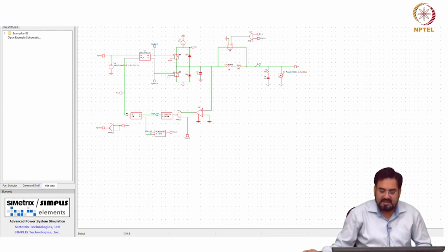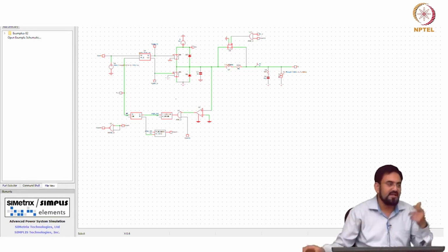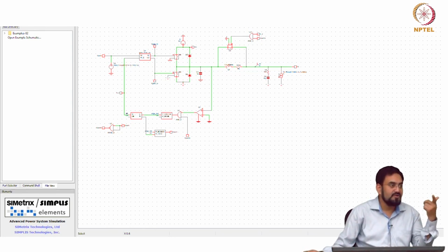Okay. If the way you have implemented the logic, high Z only remains high during the off time, then you can directly use that here. Then you do not need to get the PWM signal. But if there is any chance of high Z going high when PWM is low, then it will mistrigger and screw up everything. That is why it is always good to have a protection here. Make sure that you turn on this switch only during off time and also when high Z is triggered.